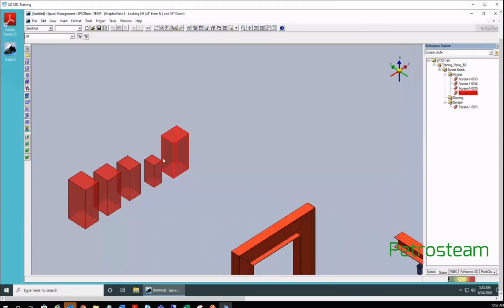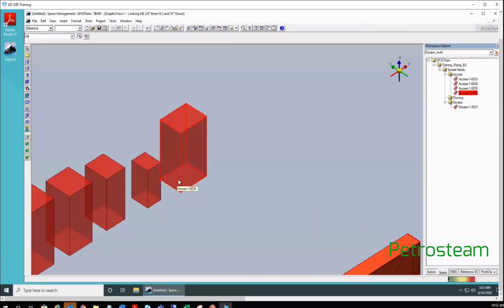Within this portion, if you model anything overnight, some piping you routed within this, then what happens overnight? Some rule checkers will be run. They are called rule checkers. The RCS process, the rule checker process, will be run overnight, and whatever new contents were modeled on that day, it will try to process and assign to the WBS volumes.